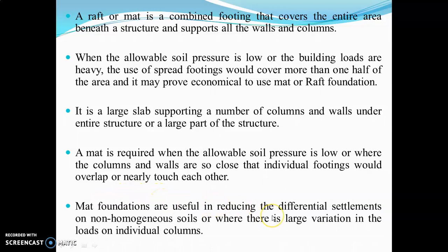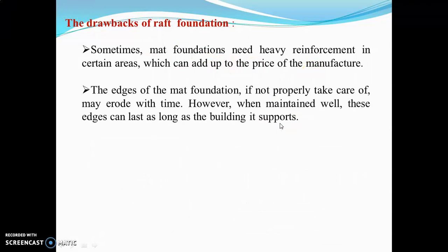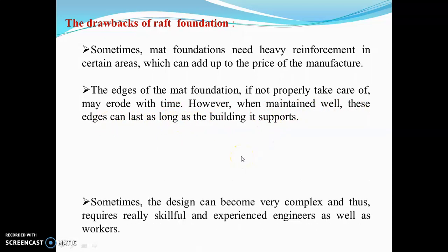Mat foundations are useful in reducing the differential settlements on non-homogeneous soils or where there is large variations in the loads on individual columns. There are some drawbacks of raft foundation, that is, sometimes mat foundations need heavy reinforcement in certain areas, which can add up to the price of the manufacture. And also the edges of the mat foundation, if not properly taken care of, may erode with time. However, when maintained well, these edges can last as long as the building it supports.